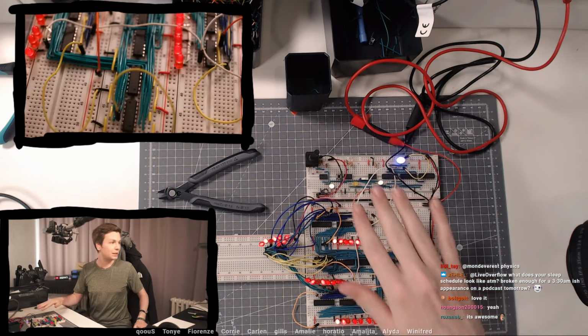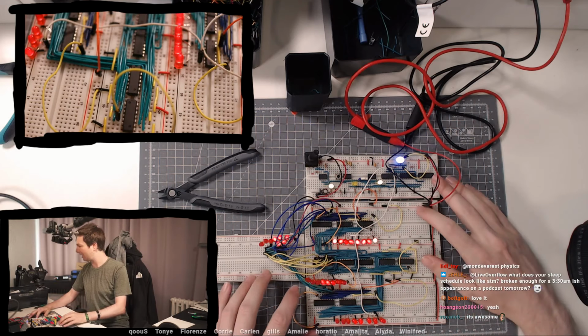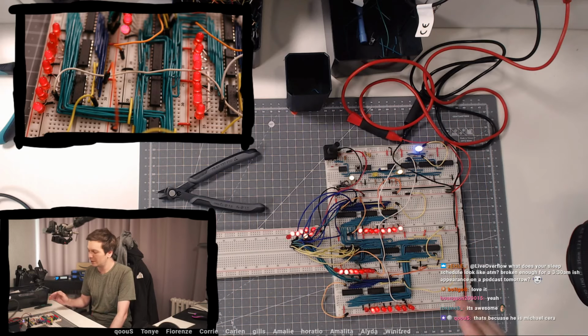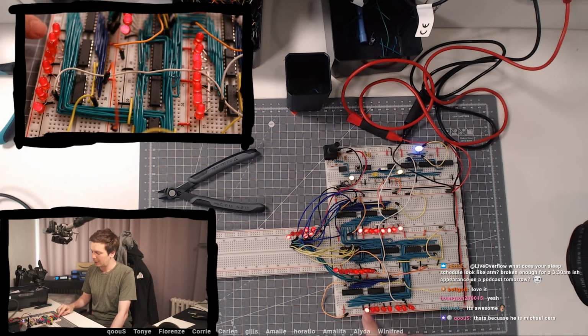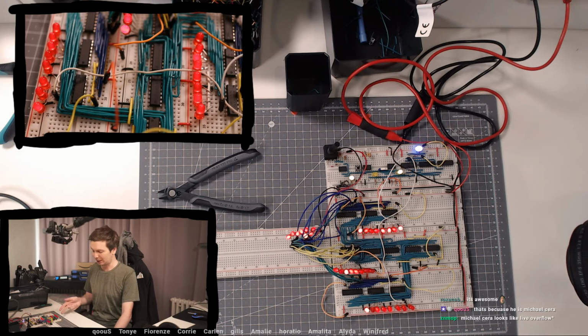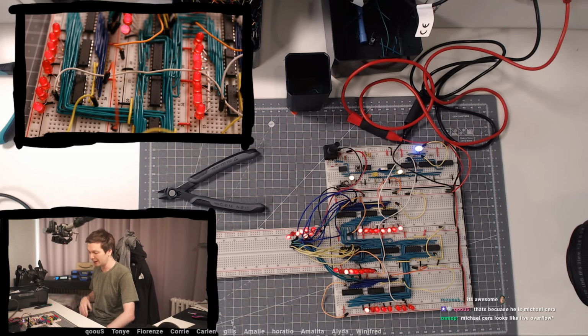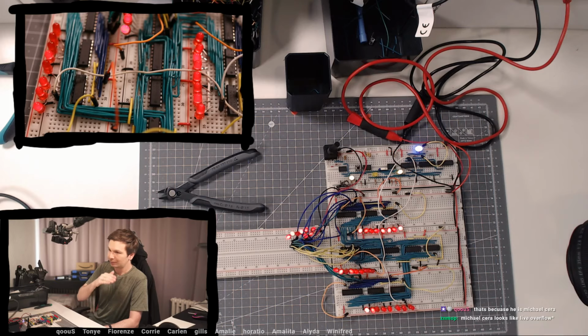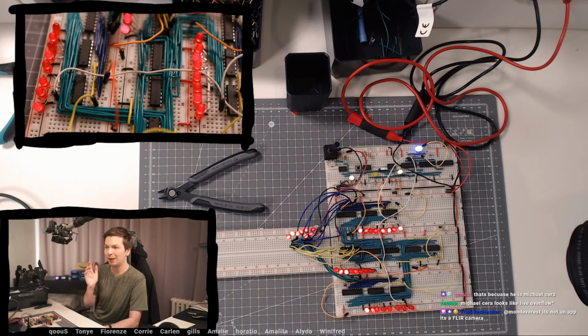As we know, the maximum frequency this currently runs at is 500 hertz. And in 8 bits you can store up to 256 values, so it counts up to 255 basically, which is roughly half of 500 hertz. In each clock cycle it will decrement once, which means with 500 hertz it will be able to count to 255 like twice per second.